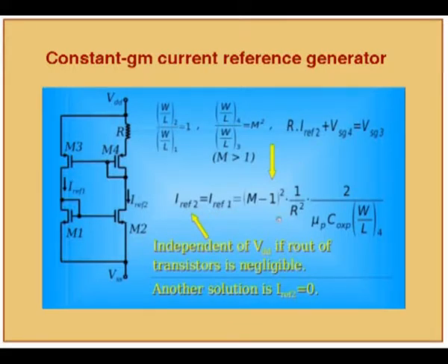However, for the sake of reliability, we should always put a startup on the chip, because if this circuit doesn't work, you know what happens? The entire chip won't work, even though everything is correct. That's why bias is very important.